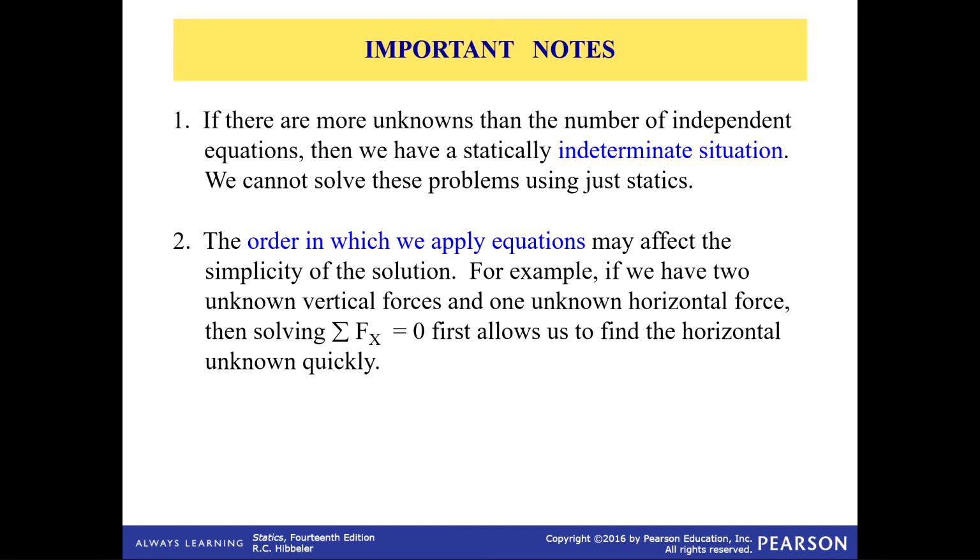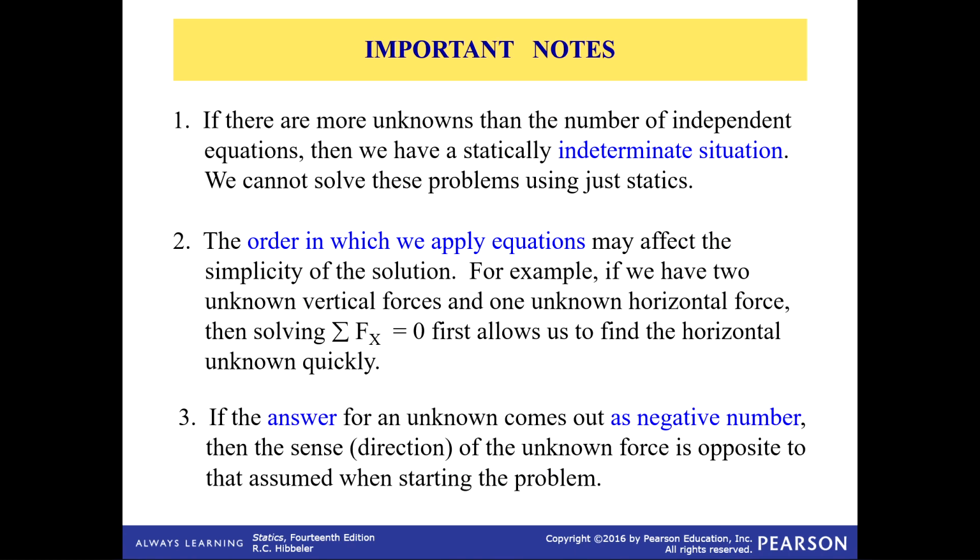Now, some caveats. There can be systems where there are more unknowns than equations. How many equations do you have in 2D? You've got 3 equations. So if you come up with 4 unknowns, you can't solve it. So you have a system that is what's called statically indeterminate. You can't solve it. The equations are listed as the sum of the forces in the X equal to 0, the sum of the forces in the Y, and the sum of the moments equals 0.